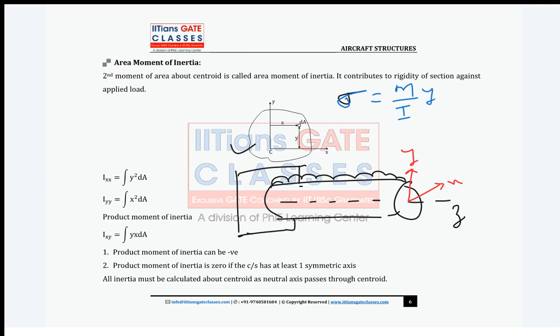Now sigma is in which direction? This bending stress is in which direction? Sonu, did you study SOM? Why is this clarity not there? See, bending stress is what? A shear stress or a normal stress? Sonu, what is this XY? XY is a cross section, right? Now, what is the Z? It's the longitudinal axis, right? So what actually is sigma? It's a normal stress, right?